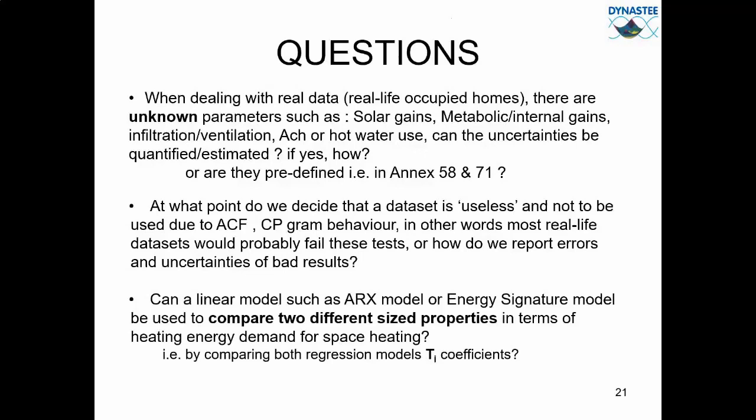So the idea is, when you have your data, you have to find the most certain data files. You have to introduce them in the model, and if you are designing the experiments, you have to try to measure as accurately as you can the main heat gains within the building for your model.